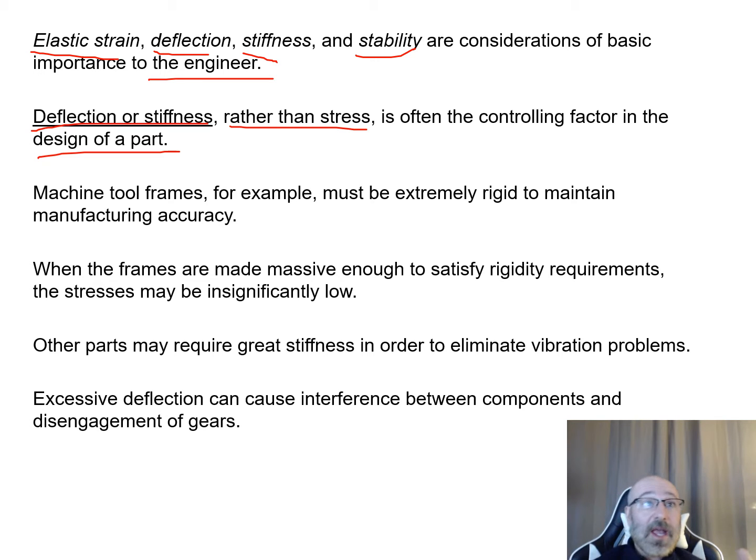So if we're looking at our deflection or our stiffness, that's something that we can actually run a test and see. So deflection test, we could do some of these different tensile testing methods. Maybe it's the 3-point bending method we're taking a look at, all those types of things, and we can get that information from our deflection and stiffness from experimental data.